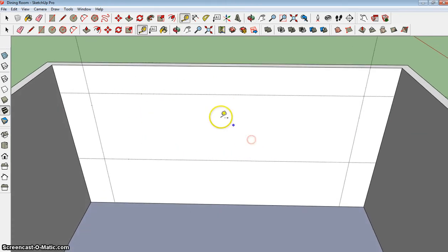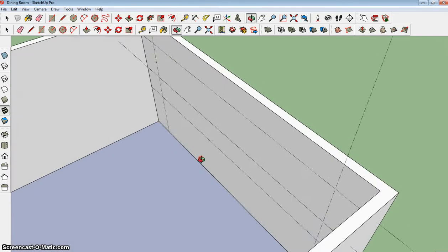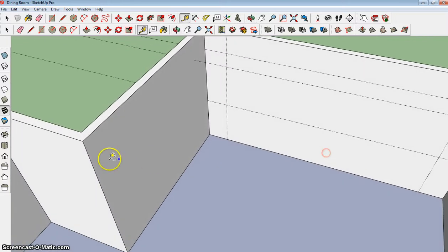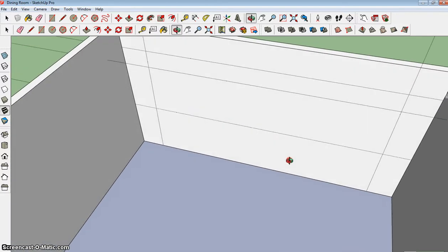And then I am going to do an arched window, so I'm going to measure down the amount I want to arch. Now be careful as you pull these lines down. Notice I have a red axis and a blue axis. Well, which one's vertical? Well, blue. So if you're pulling it out on the red axis here, it may look correct, but as you spin around and you look at where you actually place that line, you actually place it out in front, off of the wall. So typically, if you have a problem and things aren't working out, that's probably what's going on.